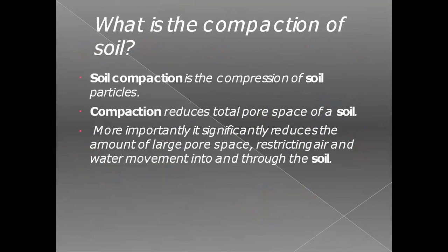If there is heavy void space between the soil particles, the soil will be compressed when we apply any load or equipment load in the construction area. So to eradicate these types of problems, we have to compact the soil.